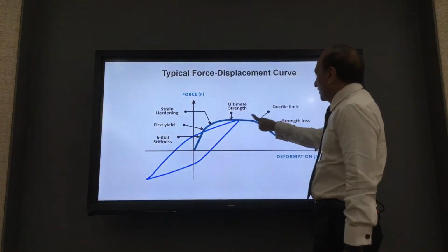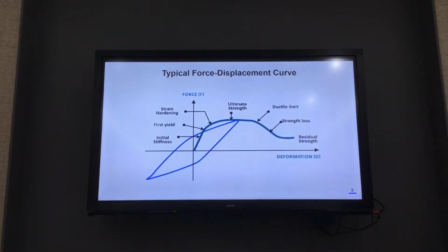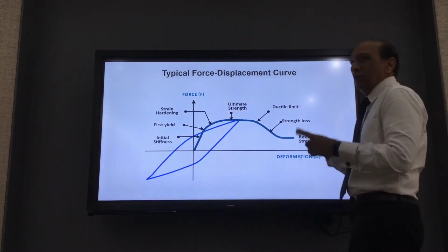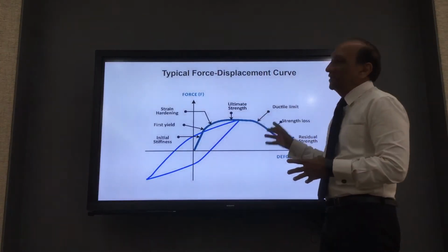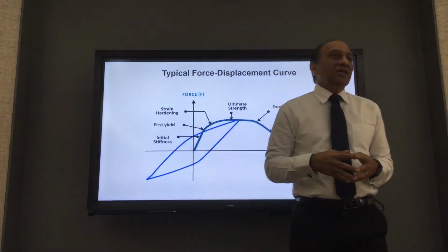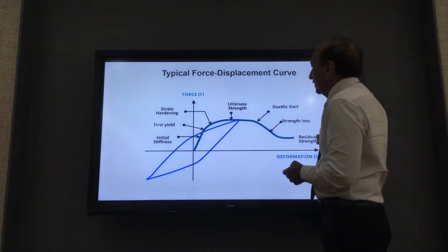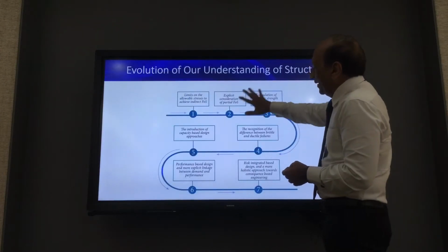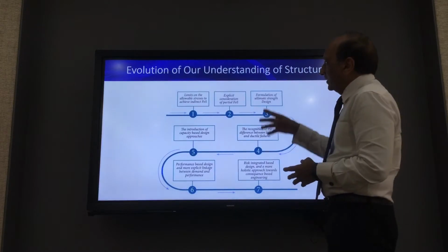But the performance-based design considers the entire response history of the structure, of the elements, of the cross-section, and of the material. So for that purpose, the ductility and the cross-section moment curvature and confinement are very important, and we have discussed this already. So if I just repeat this that we have already seen in the previous course and today,